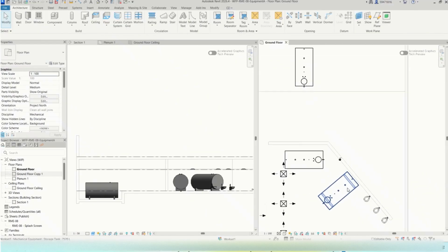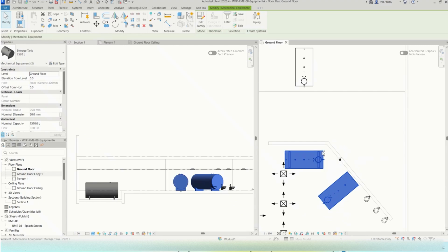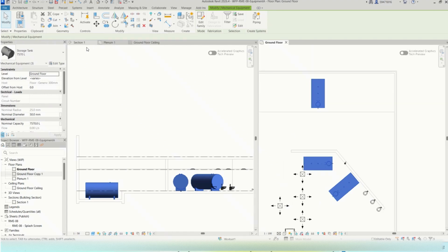Part 6. Multi-story design using the clipboard. Step 40. Select the 3 storage tanks. Select all 3 storage tanks and copy them using Ctrl+C or the copy icon. Step 41. Expand the paste options. From the clipboard panel, expand the paste button to see all paste-aligned options.